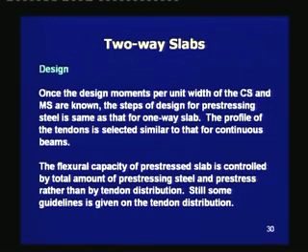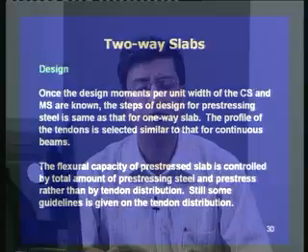It has been found that the flexural capacity of a slab is governed by the total amount of the prestressing tendons and the prestressing force. That means it is independent of the distribution of the prestressing tendons. Hence, there is flexibility in placing the prestressing tendons, but still there are some guidelines to distribute the tendon.